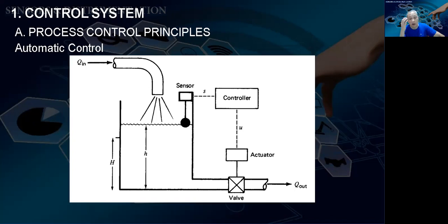As you look at this now, the third one is automatic control. Let me show you with my laser. There are sensors here to sense the level of the water, and this is being fed back into the controller. So the controller knows the level of water in the tank. With that information, the controller will give a command to the actuators here. The actuators will open and close the valve according to the control action given to them. So by this, it is automatic. You just type in, probably log into your computer, and say the level is this, and you want to change it automatically. And whatever disturbance comes in, the water level will try to be maintained at that desired point.